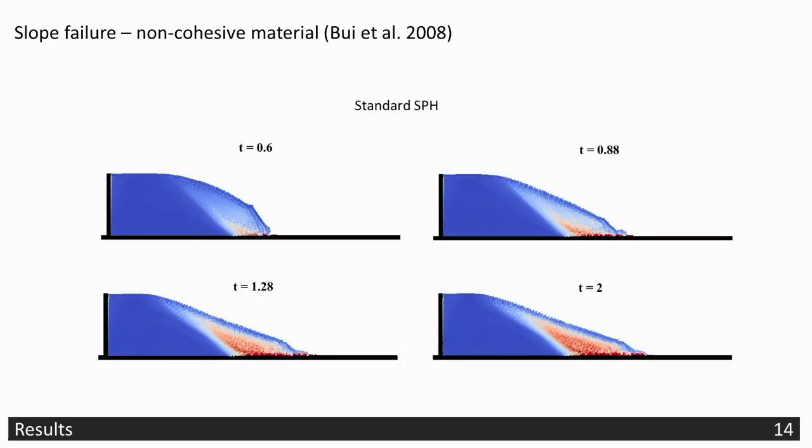So these problems that I spoke about were mainly relevant to landslide failure mechanisms, but then I also wanted to test the numerical method to apply it to situations that are more representative of landslide propagation, because having the stress points and the nodes, that's never been applied to flow type problems, so problems that behave as a fluid. So this problem is the same as the one I just described, except that whereas that material had cohesion, this material doesn't have any cohesion. So this just basically is a sand, and it has a much larger runout, reaches higher velocities than the previous example.